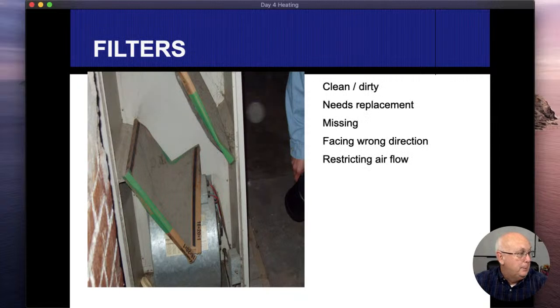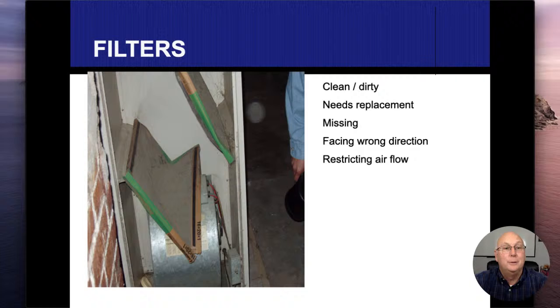So, last thing we're going to chat about, and then I'm going to finish up here, is going to be filters. Again, I think I chatted on those before quite a bit. I can't encourage you enough to talk to your clients about the importance of changing out these filters, keeping them clean. This one actually got so dirty that it folded in on itself and collapsed. And we don't know how long it was like this, too. So remember the order of airflow, going back a little bit: filter, fan, heat exchanger, and then the air conditioning coil.